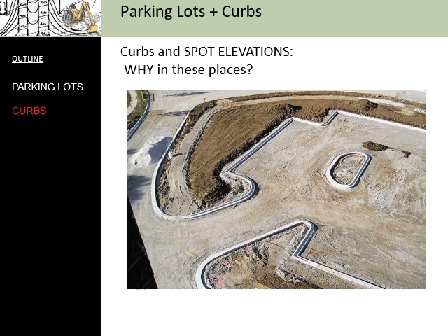So it's often very helpful to look at the construction of a parking lot to understand why we need these spot elevations and where they're going to be located. So in this example, you can see the curb is poured before the parking lot asphalt is laid. And so we have to have the correct elevations for these known by the contractor in order to get the elevations of the curbs correct.